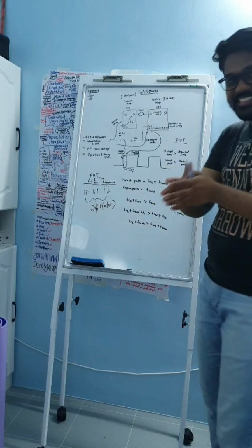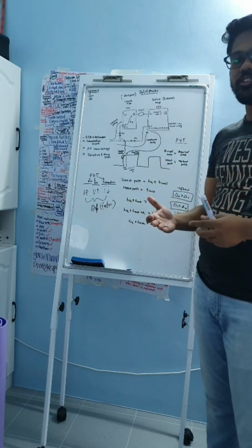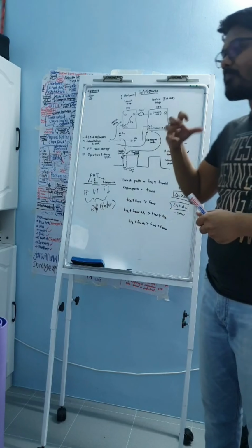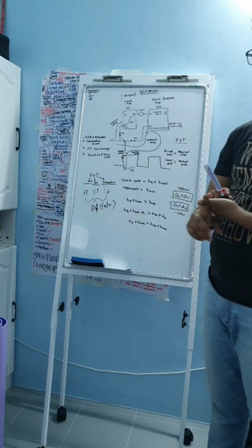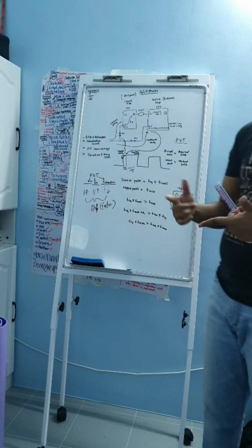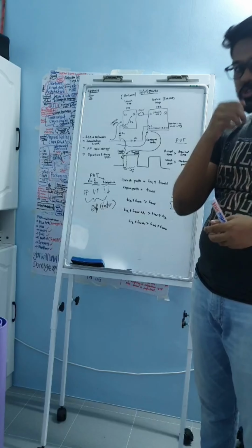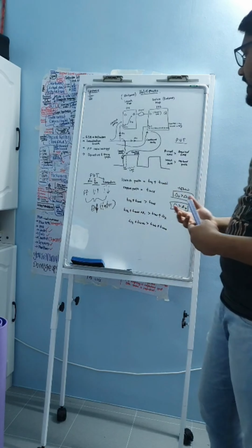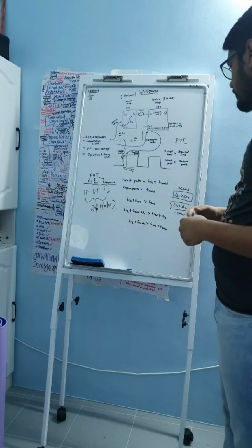That's the reason in the CTS stage you introduce useful skew a lot. Later on, post CTS, the tools would try to fix your violations. That's why you would see more buffers being added later on. That's where your violations get fixed, but it creates an increase in power dissipation and area. Obviously, the area increase does not mean your floor plan increases. It means your utilization rate keeps increasing. It depends on how much utilization you have with the design, how much you allocated at the beginning, and how much you allocate at a later stage.